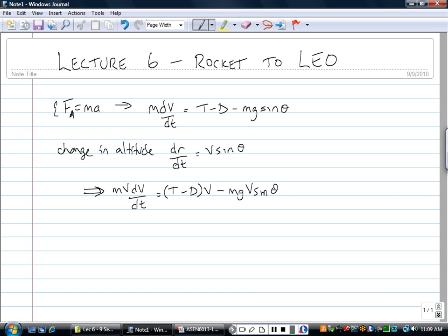Anybody know what thrust minus drag times v is? Yeah, it's essentially your power term. So it's your net power, your power available. If your drag equals thrust, you have no power available. Rearrange again, pull the v in. So hopefully in another lecture or two we'll get caught up and I can slow down and write legibly. Okay, so we substitute our dr/dt, where r is our altitude term, our radius term. Just make a note in there so everything makes some sense.